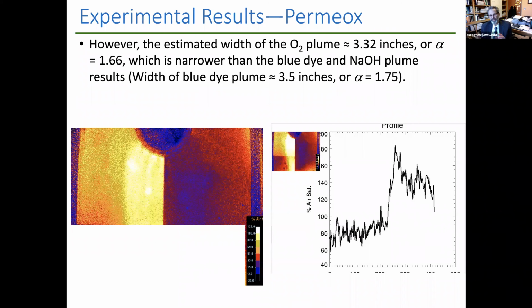So if molecular diffusion was really important at this velocity, then that concentration effect, I imagine, could be more important. If the mechanical dispersion was more important, then the dispersivity, which would be the same in all of these cases, would be the important parameter, right? And I'm guessing that at this velocity of 10 meters per day, and I didn't do this calculation yet, but it'd be a good thing to look at, we're probably in a range where mechanical dispersion is dominant over diffusion.